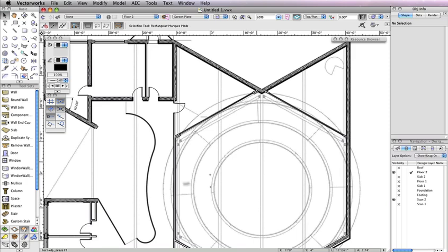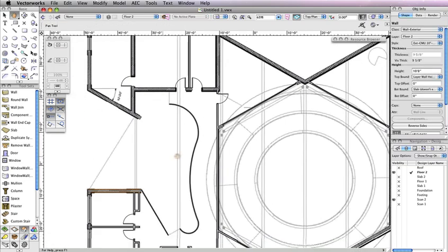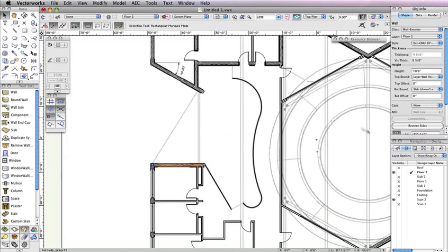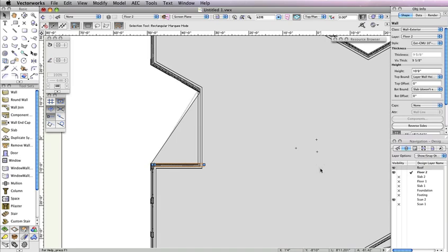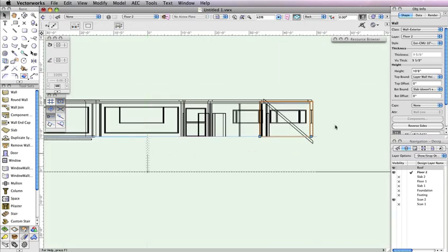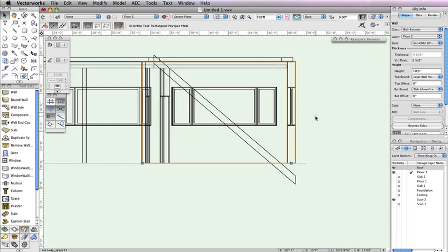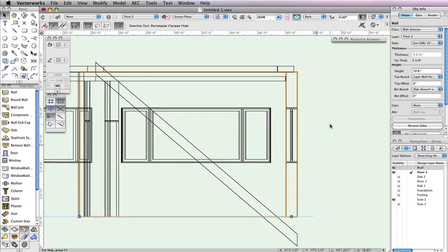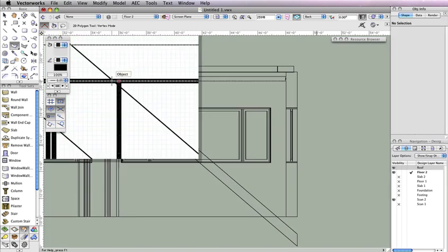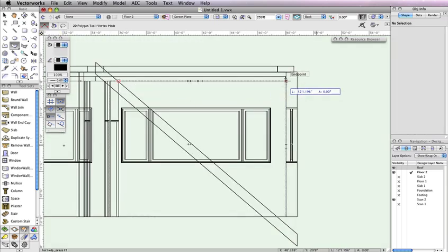First, select this wall. Then, in the navigation palette, set the roof layer to visible. Also, switch to a back view from the view bar and zoom in on the highlighted wall. You'll be creating a triangular-shaped window in this wall. Select the Polygon tool from the basic tool palette and make sure Vertex mode is enabled. Now, click at the same 3 points as shown. Don't forget to use the snap loop to temporarily zoom in for a better view.